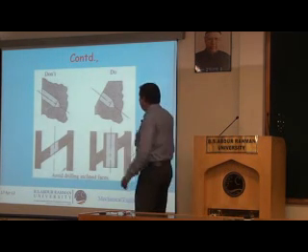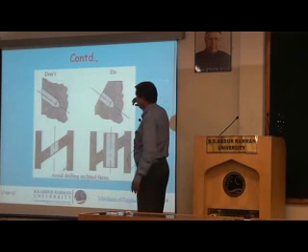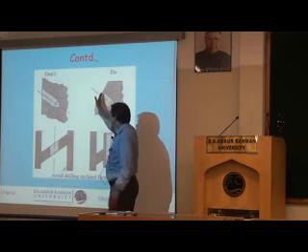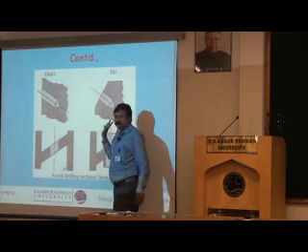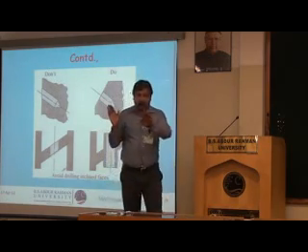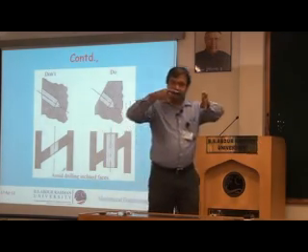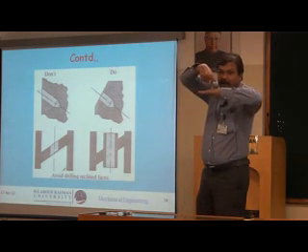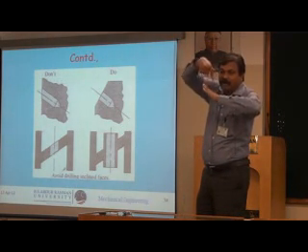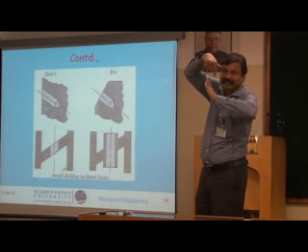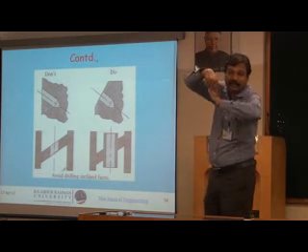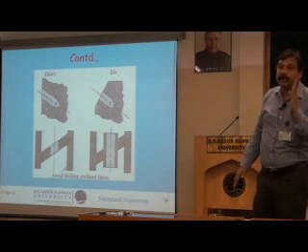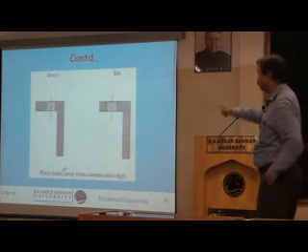Similarly, don't try to drill a hole at an angle. Now, please remember the drill must always come perpendicular to the surface. If you want to drill a hole, the drill bit must be perpendicular to the surface. If you want to drill a hole like this, on a surface like this, it is very, very difficult. The drill bit must be positioned always perpendicular to the surface when you want to drill.